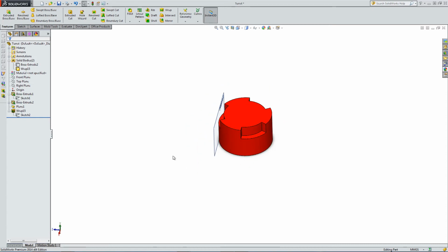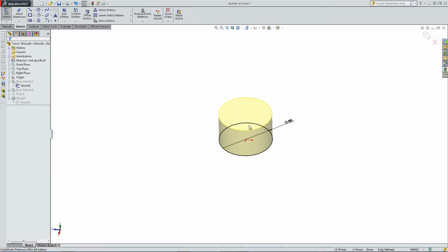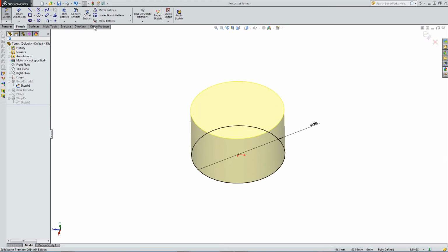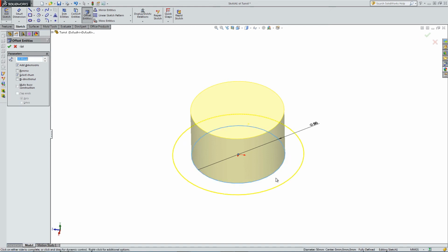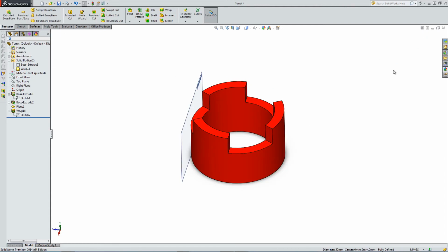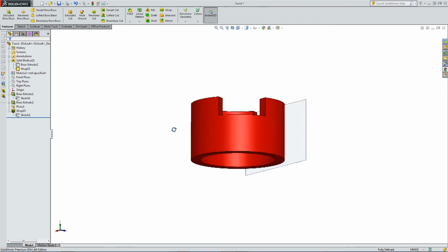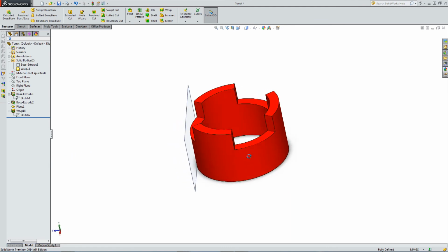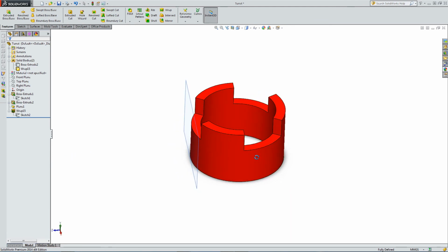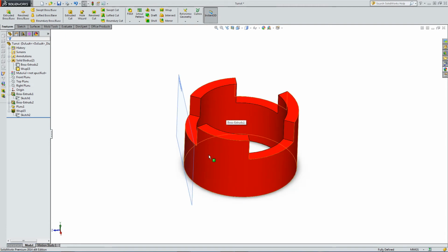So we could modify the shape. Let's say I'm going to offset another circle inside this shape. Reverse it. We know the emboss is 5 mil, so let's make this 5 mil. Depending on the shape we make, it affects our wrap. So the wrap came in 5 mil, it's taken out the material, and we now have a tube. So there's different ways you can interact with wraps.